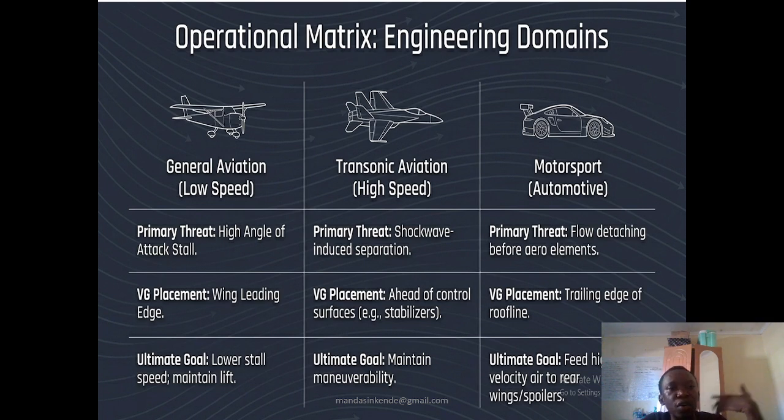Apart from low speed, it also allows us to have higher angles of attack. Angles of attack are how the aircraft pitches up. The higher it can pitch, the easier it is for it to climb. Now, as it pitches more, the chances of that wake being produced are high, and therefore the aircraft can stall. Now, with vortex generators, the airflow will still stay attached to the surface despite that pitch.